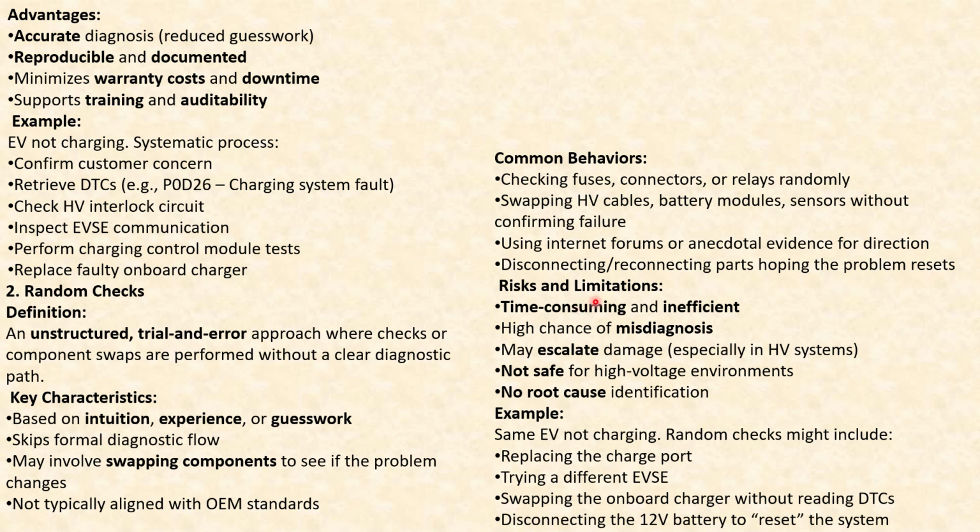But what are the disadvantages of this? What are the risks? It is time consuming and inefficient, with a high chance of misdiagnosis. It may escalate damage, especially in high voltage systems, is not safe for high voltage environments, and gives no root cause identification. The only advantage I see is if the technician is very experienced and can zero in on the problem in an expert manner, then he can save time. That's the only advantage as far as I am concerned.